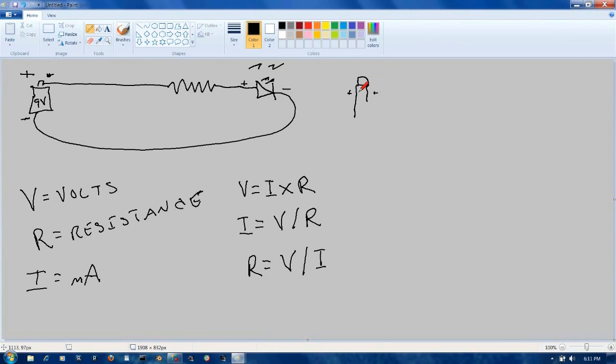Okay, so we have this LED. Yeah, we need a resistor. We don't know, but most components, especially when we get to integrated circuits, have data sheets. The data sheets tell you certain things. It tells you what volts you can use, how much milliamps it can draw. Let's assume that it says it can take 3 volts. And most LEDs can take 3 volts. But that does us no good. We have volts and volts, we're not figuring out anything. What we need from this is how many milliamps it draws. How many milliamps does this little LED use?